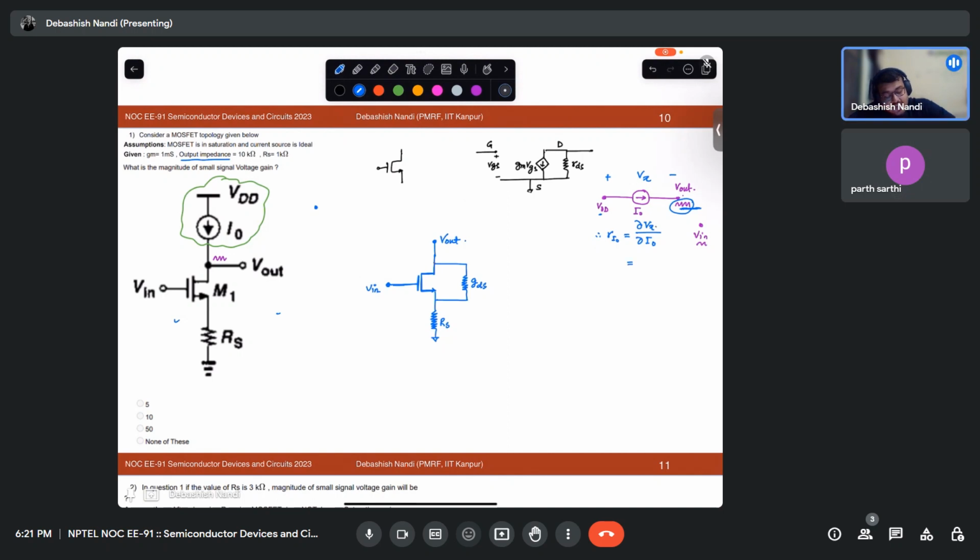So what is your delta Vx? This variation, let's say delta V. And what is your delta I0? 0. So what is your impedance? Infinite. So what does an infinite resistance mean? Open circuit. So you told short circuit, right?